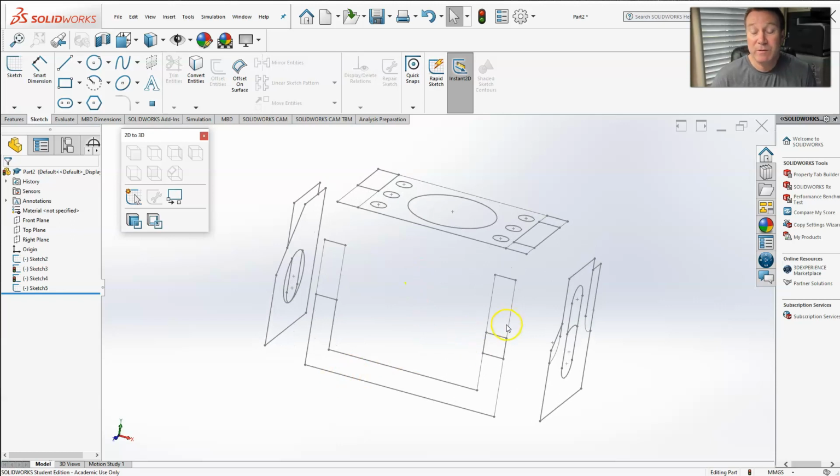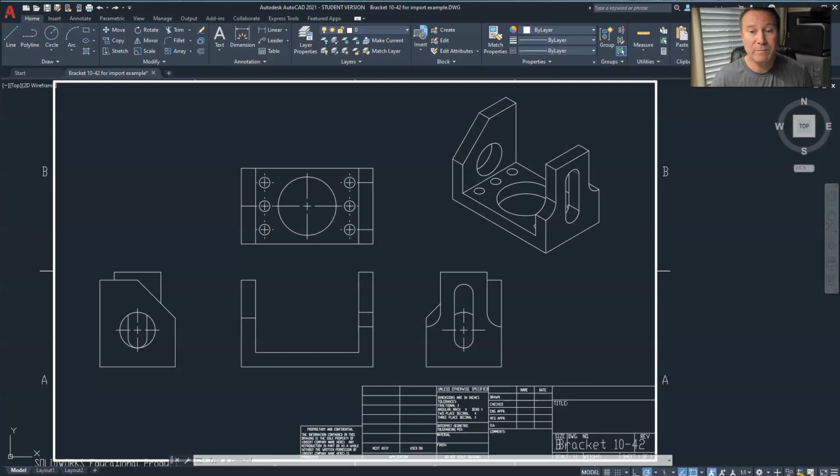If I was going to machine this, I see from the original drawing, let's bring that one back, original drawing, if you look at the isometric, it looks just like a U-channel. If you had an actual U-channel with the exact specifications, the width, you can just cut the width of it out, and then 3 machine operations: cut on this side, cut on this side, and then cut and drill on the bottom.